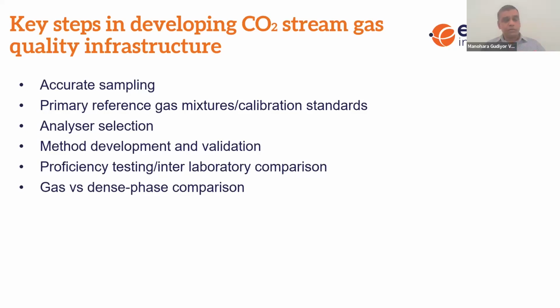This is generally what we do, but for CO2 purity we have an additional challenge, which I'm sure most of you are aware of: doing a gas phase analysis versus dense phase comparison. Whether we can rely on gas phase measurements for measuring what's happening in the dense phase. At this point in time, we have a capability, or at least a possibility, of developing a gas phase infrastructure for analyzing components in gas phase.